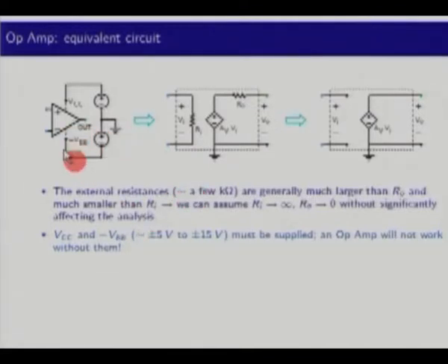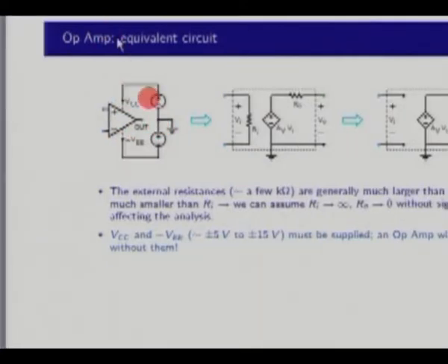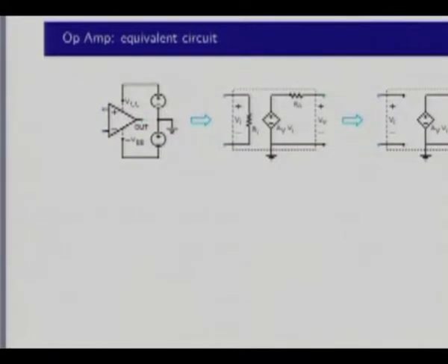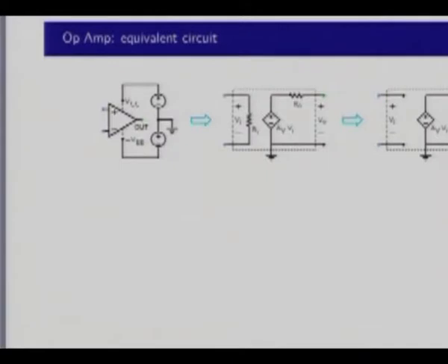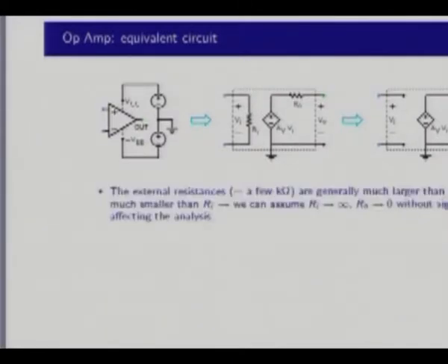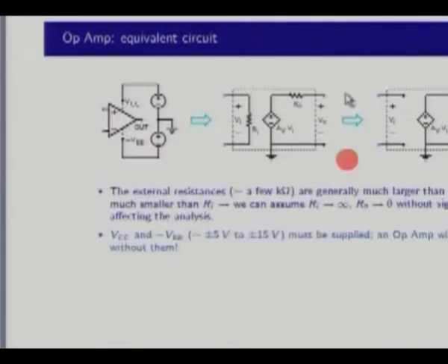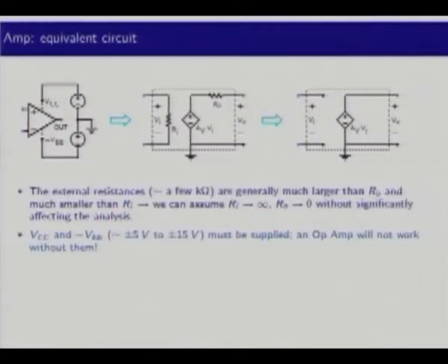Ground actually is in the op amp. If you notice, there is no explicit pin for the ground, right? So all you have is this VCC rail here on top and minus VEE rail at the bottom, and therefore there is no connection for 741 for ground, and therefore sometimes people don't connect ground anywhere and then they get into trouble. When students do these experiments for the first time, they will often make this mistake. That's why it's important to point these out.